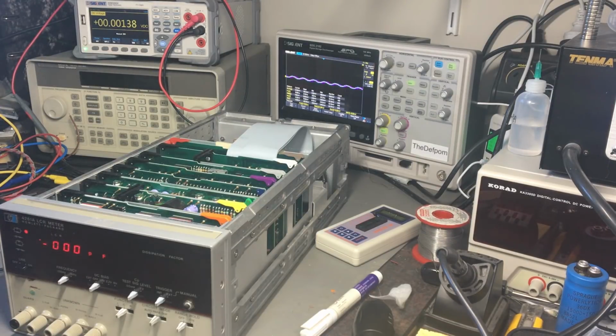Okay, so the next part is as follows. A4 ball check apparently. Now I have to set it on capacitance range, which I've got set. I need to have it on parallel, which I've got set. No connections on the front, apart from the jumper link, so that doesn't specify what to do with those, but I've assumed they're supposed to be made, so I've left them made. I have to observe the waveform at the HCUR terminal, which is this one. So I might as well stick it on that bar there. And there we go, that is a waveform. Okay, although it's an awfully noisy waveform, there is a waveform.